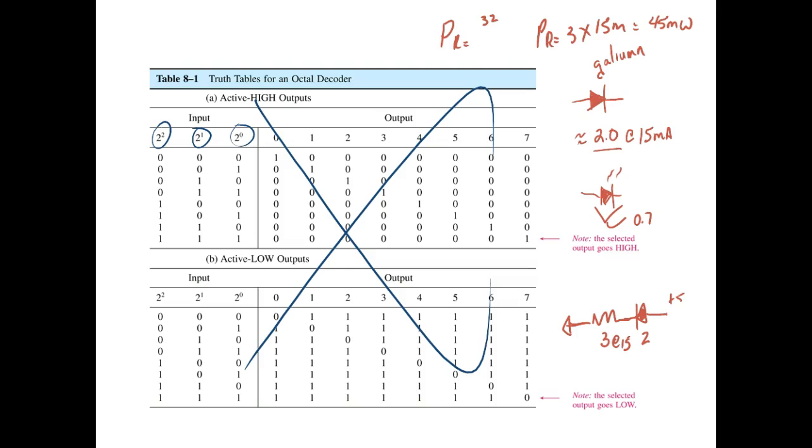I don't have any SIPs, but I do have some DIPs. When we need a lot of resistors, we use a lot of pull-up and pull-down resistors. The output of my gate for a load can be a maximum of about 16 milliamps, so I don't even need a quarter watt or an eighth of a watt resistor for that.